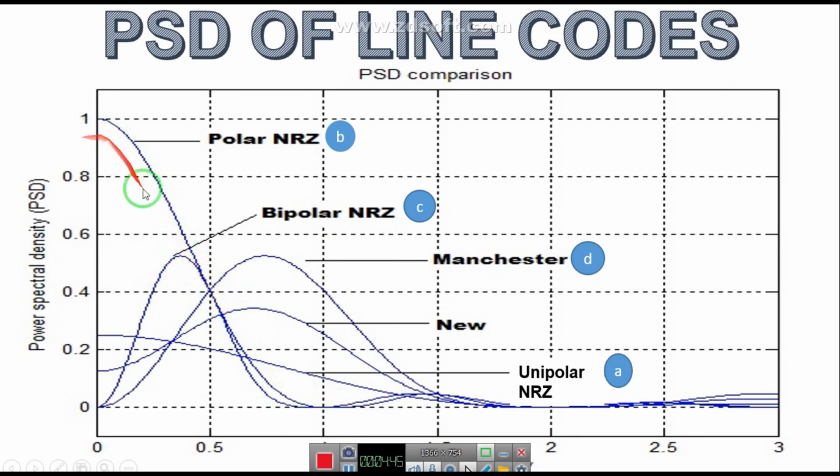Why are we using a sinc function? Instead of transmitting a rectangular pulse, in order to reduce the ISI effect, it is better to transmit a sinc function. So what is ISI? It is there in the lecture, so today we are also going to discuss ISI. The main lobe basically extends up to the rate of 1 by T.